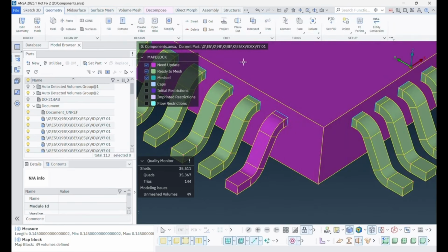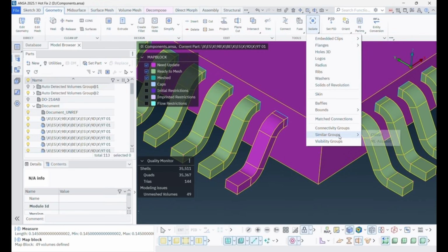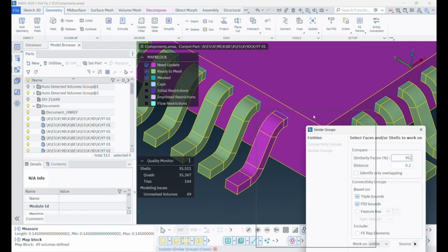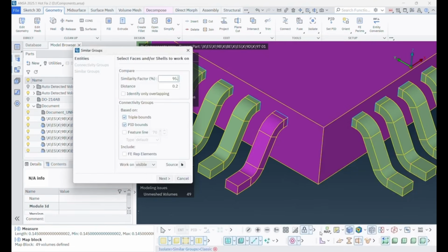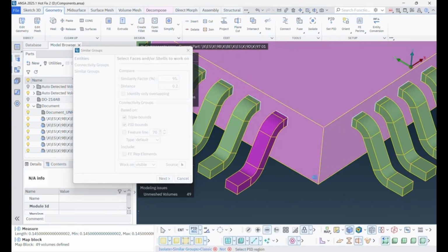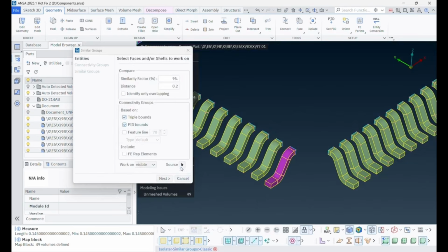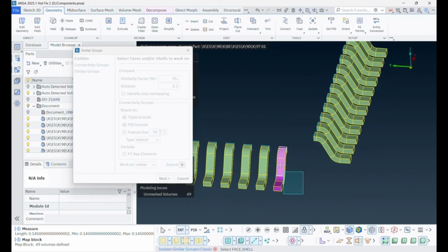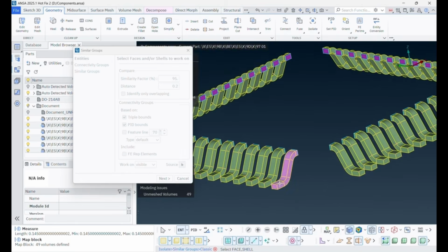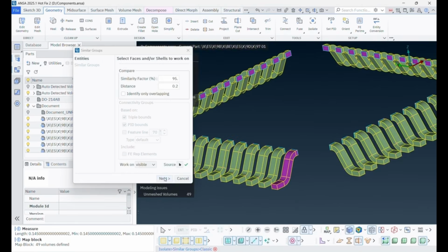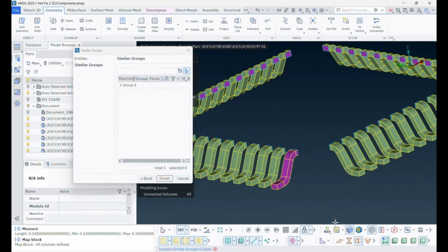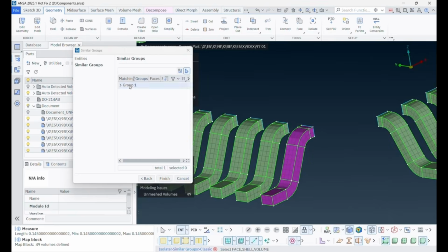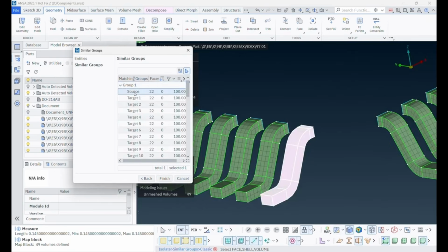Once the mesh quality of one pin meets the requirements, use isolate similar groups to identify similar regions. Then use copy entities to copy the processing result, which can greatly reduce repetitive operations.